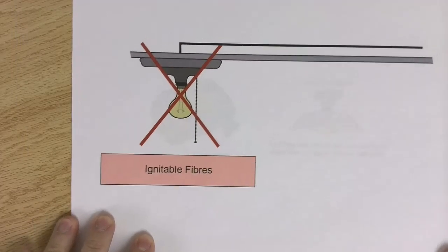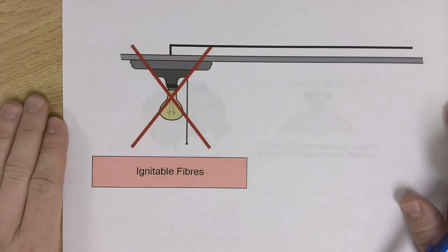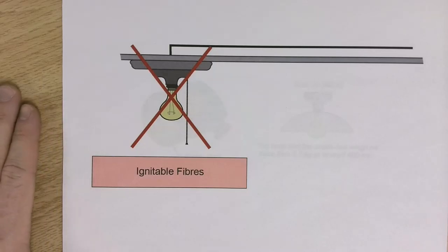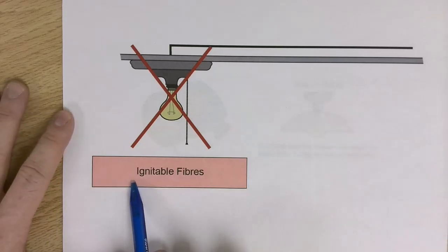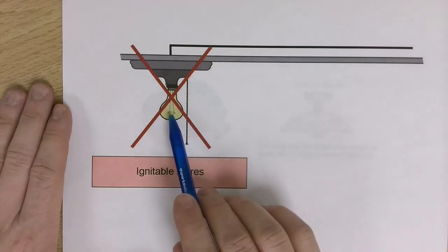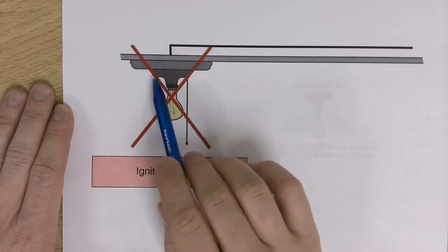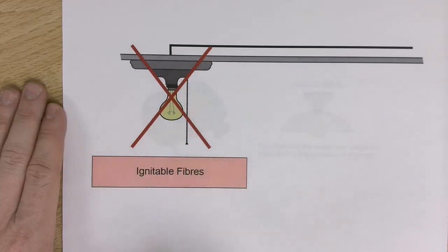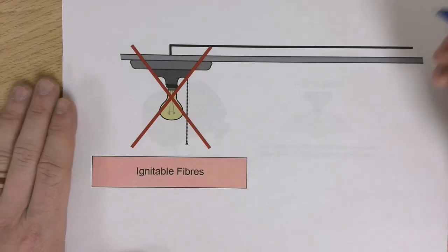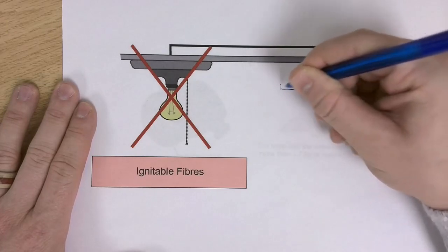Now, some lamps create heat when we use them as a light source, as we talked about. And the codebook is going to tell us that if it's above ignitable fibers, such as in a closet, you cannot have a bare lamp, this type of light. If you had a light, sometimes called a boob light, they look like this.